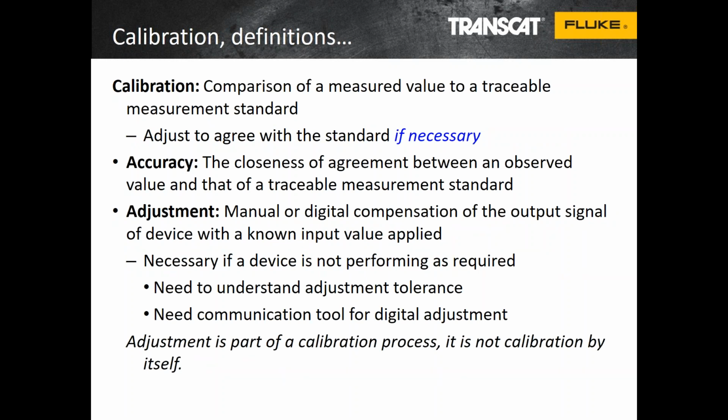So some definitions on calibration. Calibration is, by definition, the comparison of a measured value to a traceable measurement standard. Notice the definition of calibration does not have the word adjustment in it. Adjustment to agree with the standard is required if the comparison shows that the actual value is unsatisfactory. So adjusting to agree can be part of the calibration process, but is not defined as calibration. Calibration is simply the comparison.